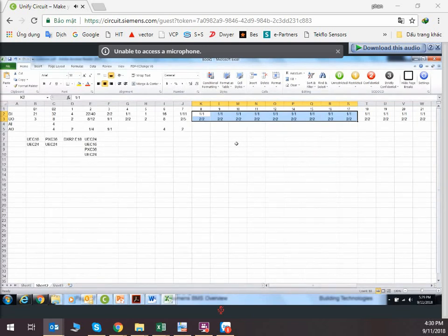Okay, for PXC3, you need to use ABT Pro in order to configure it. For DXR, you can use Site, you can use Pro. But if you are using DXR and PXC3 for a lot of points, most likely you'll be using ABT Pro. Okay, but if you're using BACnet Beam, ABT Site will be sufficient.